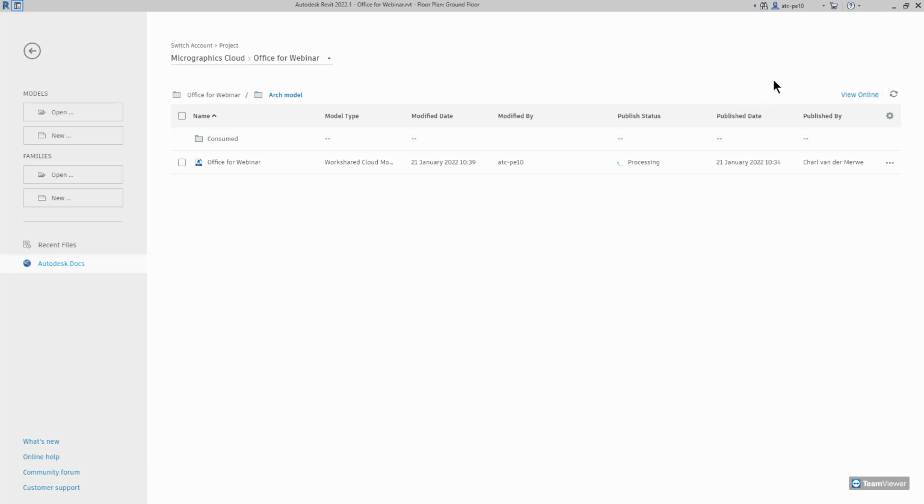Right, okay, so while that's going, I will now sign out again, but I need to make sure that that is finished. As you can see, it's not instant. When you publish, or when you sync to Central, just wait a couple of minutes. There is a lag perhaps with the upload and the system being updated, especially if it's a large project. Give it an hour before someone else is publishing. So rather than every 10 minutes, give it an hour in between.